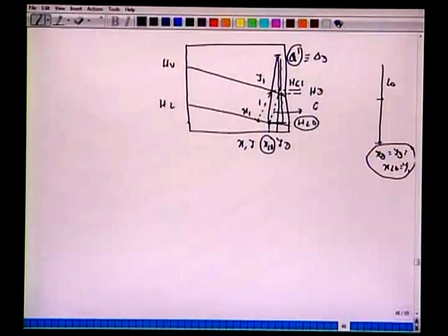The first line is the condenser, the partial condenser, a theoretical stage. The second tie line is actually plate number 1, and then onward we have number 2, number 3, etc. The reflux ratio which we are obtaining is the projection from the first operating line which we have drawn from here. Take the projection, that will be Hg1 minus HL0. So, reflux ratio R is Q dash minus Hg1, the enthalpy of the vapor leaving the first stage, which is here, not here. Do not make a mistake.